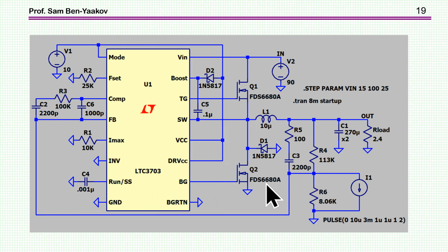What I did is add an excitation, injecting current into this point. This is like an excitation to the reference. We don't have access to the reference, so this is like having a change in the reference. I'm putting in a current source, so the impedance is not changing and the voltage divider is the same.